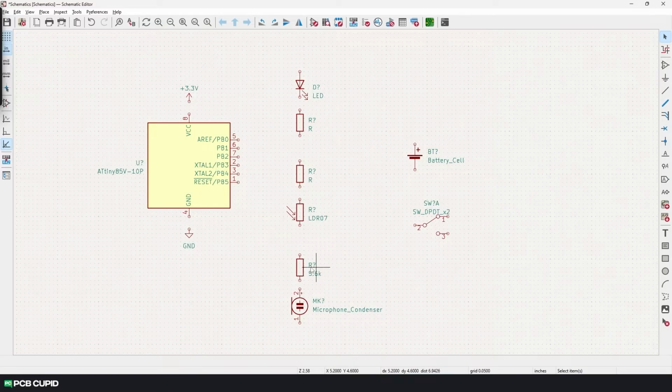Seems like only the single R value changed. What about the R and the question mark? These extra values are called designators, and they are currently shown with a question mark because I have turned off the automatic annotation. Once we complete the circuit, I'll show you how to automatically number everything together at once.